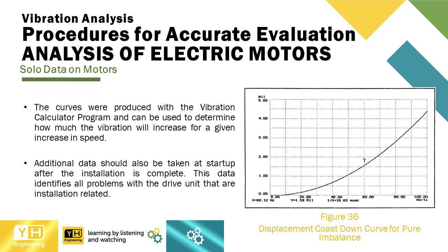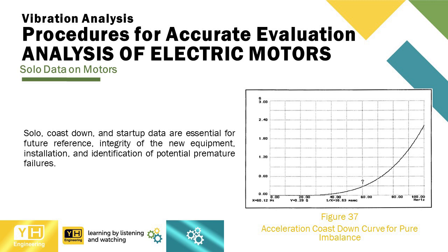Additional data should also be taken at startup after the installation is complete. This data identifies all problems with the drive unit that are installation related. Solo, coast-down, and startup data are essential for future reference, integrity of the new equipment installation, and identification of potential premature failures.